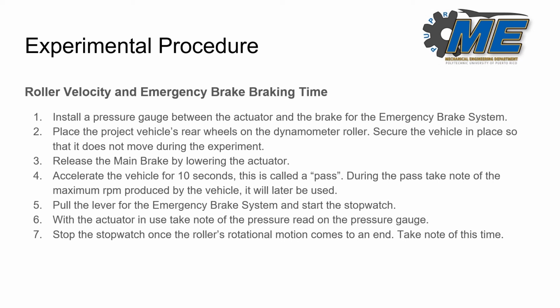Step 6, with the actuator in use, take note of the pressure reading on the pressure gauge. And the last step, step 7, stop the stopwatch once the roller's rotational motion comes to an end. Take note of this time.